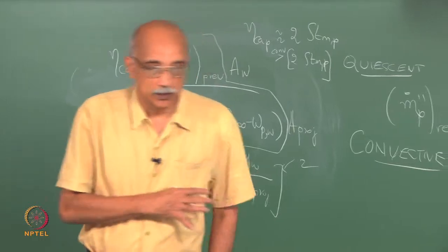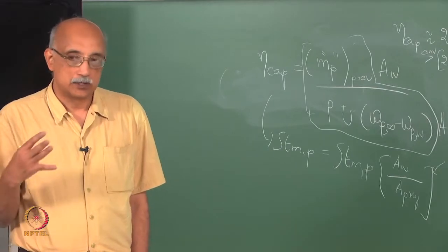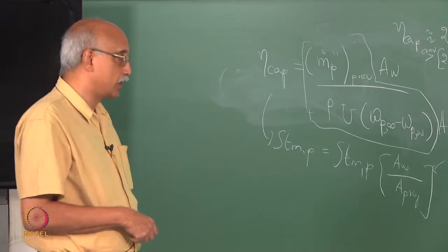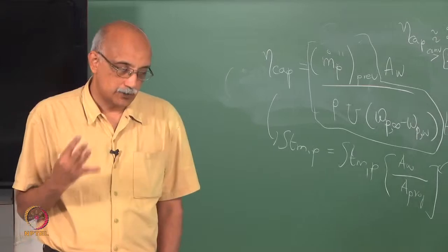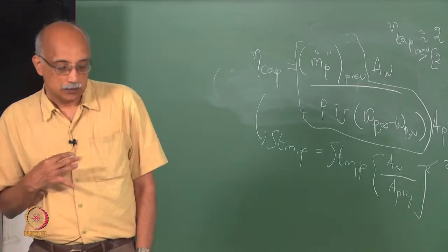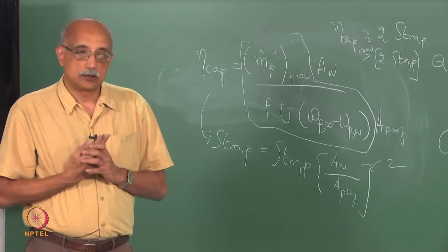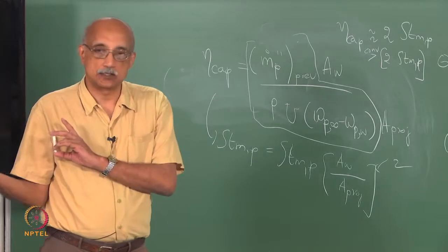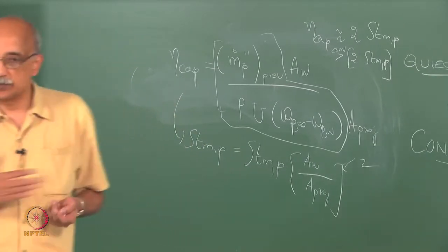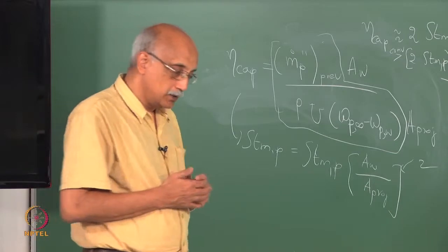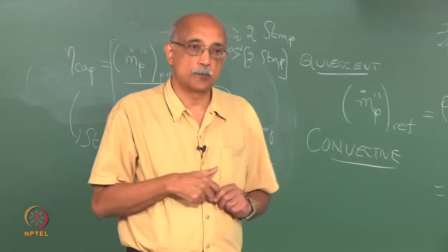This makes it very convenient for us to do our experimentation on heat transfer phenomenon and use our data to then draw conclusions about the mass transfer phenomena that are present. This becomes especially important when you have to do measurements in situ, where you do not have the luxury of drawing samples and doing your analysis offline, where, for example, this may be a flow situation in a pipeline where particles are being conveyed in slurry form, and you need to be able to obtain real time data by injecting a probe right into the flow path.